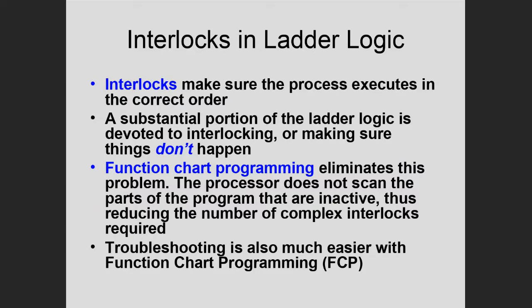And then there's something called an interlock. Now, if any of you are co-oping and working in some kind of industrial environment, they have physical interlocks. An interlock is just a way of preventing something from happening. A physical interlock could be something as simple as a switch in a cabinet, and that cabinet is lockable. You can tag it out so it can't be moved. You can lock it. An interlock might be a password on the screen. So, any way of preventing something from happening.